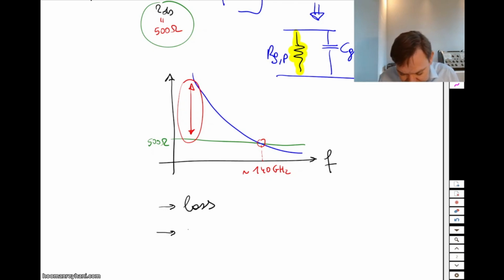And a second constraint is bandwidth. I mean, the higher the distance in ohms that you try to bridge on a Smith chart, for example. You can also visualize this nicely on a Smith chart. Also something that we're going to cover during the course. But the problem if those impedances are too far away from each other is bandwidth. So these are two reasons why nobody is using complex conjugate matching at RF frequencies, but we are using it extensively at millimeter wave frequencies. And I would say the crossing frequency is somewhere around 10, 20, 30 gigahertz.